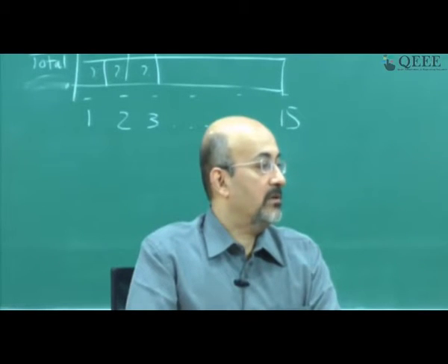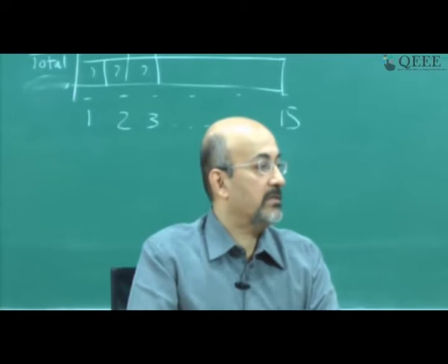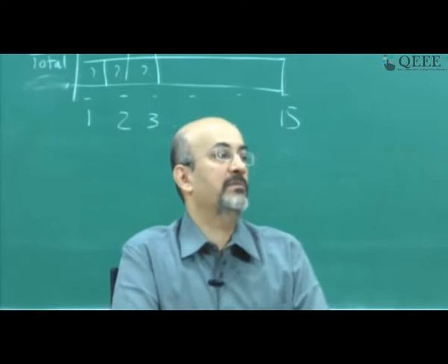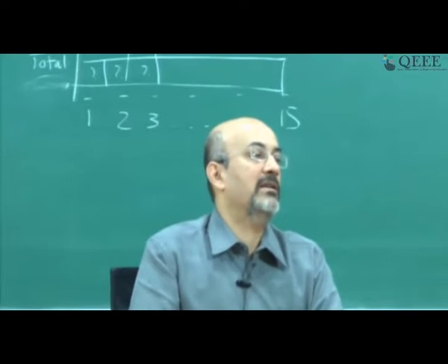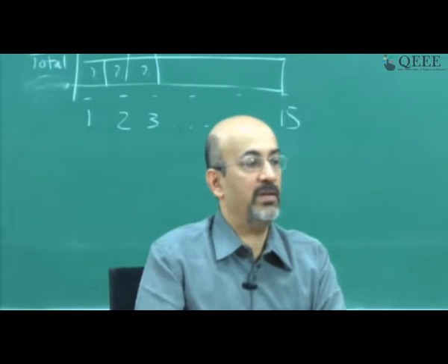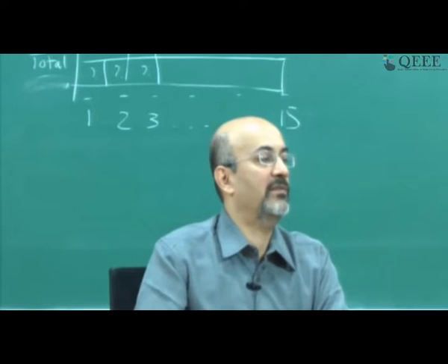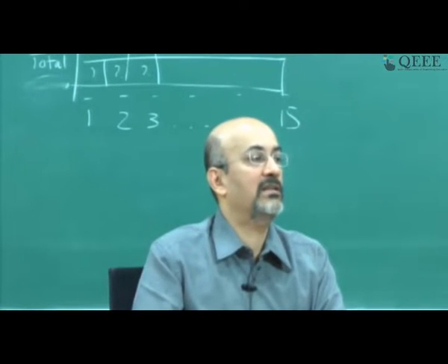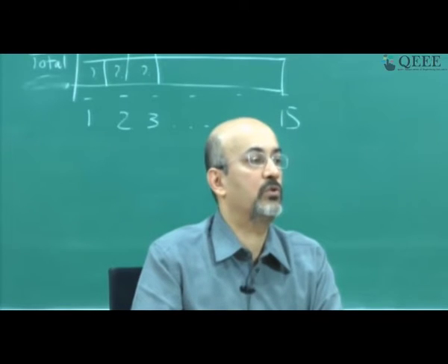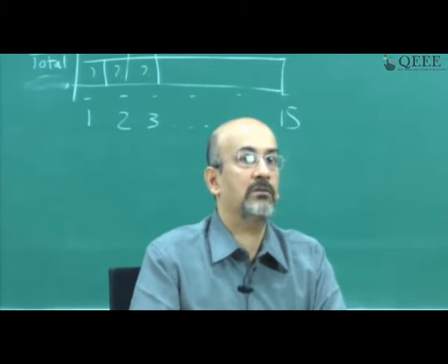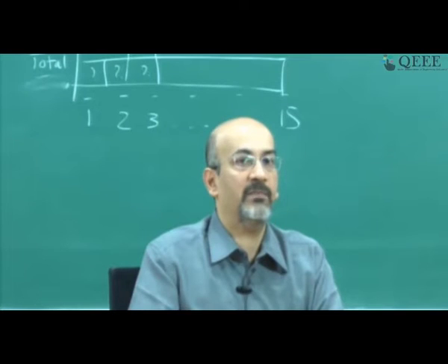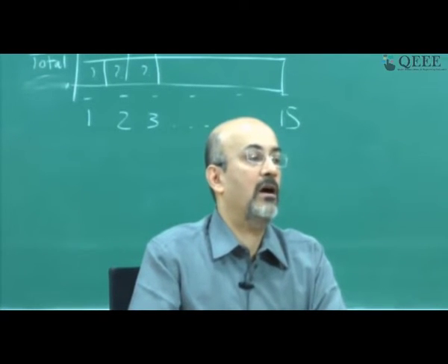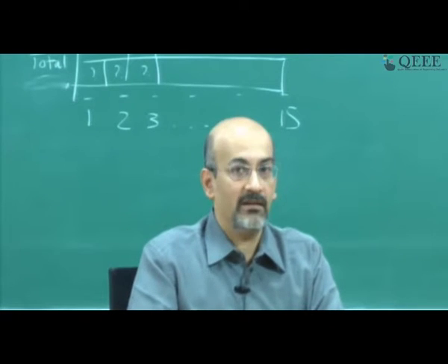Can late start control cash flow? Will it affect overall project cost? So typically with late start, yes, like we said, there are two problems. Late start doesn't mean that my cash flow is fully controlled. So please don't assume that I'm suggesting everything should go to late start in order to control cash flow. All I'm trying to illustrate here is that float can be used to balance out the resources so that over-allocation can be resolved. Float can be used later on even to bring in resource leveling.